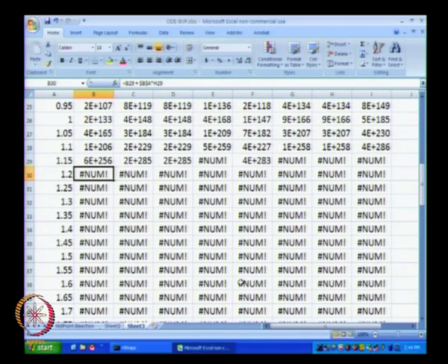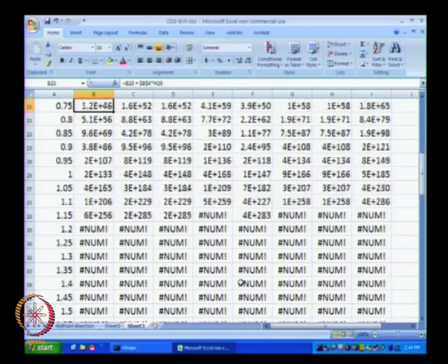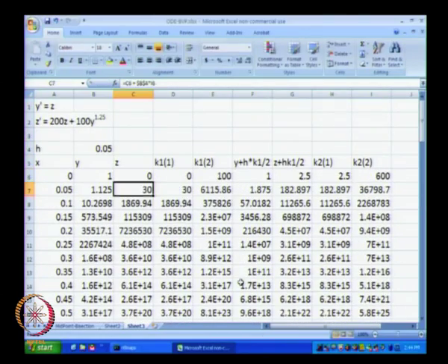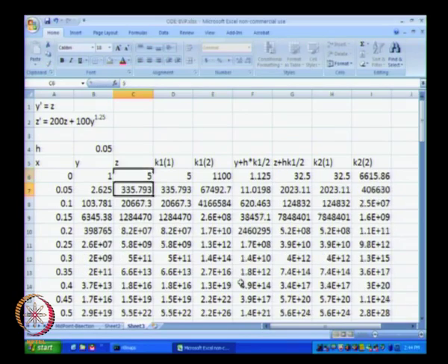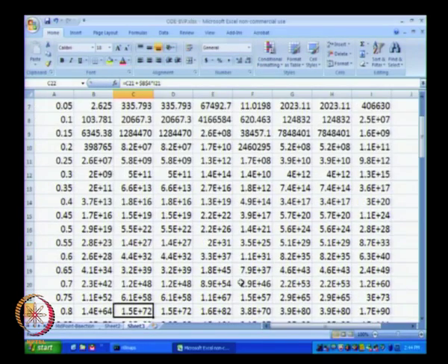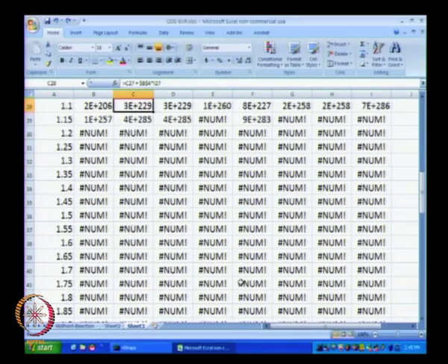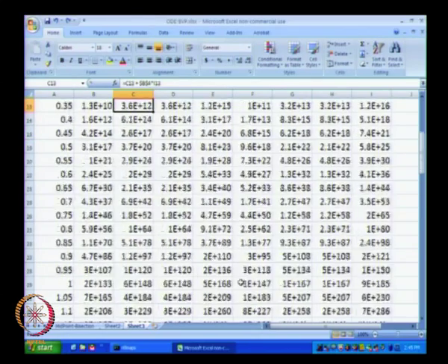This, why we get this as an error over here is because the number that we would get over here based on the numerical value should be infinity. Let us try another value z equal to 0, and we will see the same problem. Let us try z equal to 5 and we will see the same problem. So, let us say z equal to 0, we will see that after about 1.2 meters of length we get the concentration predicted as infinity.